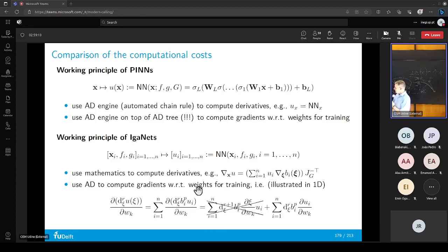Maybe here, from physical to parameter space, the Jacobian, etc., comes in, but this is all standard in FEM. We do it all the time. Bottom line, if we need a second or third derivative, it does not involve a single AD run. We are just shifting all these derivatives to the test function. That's it. So calculating derivatives with respect to physical coordinates comes kind of for free.